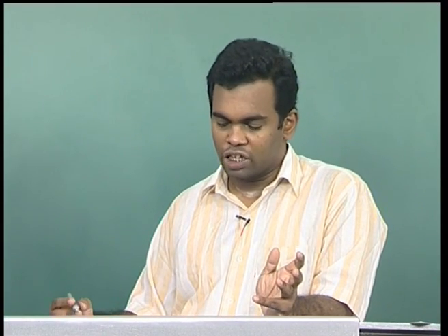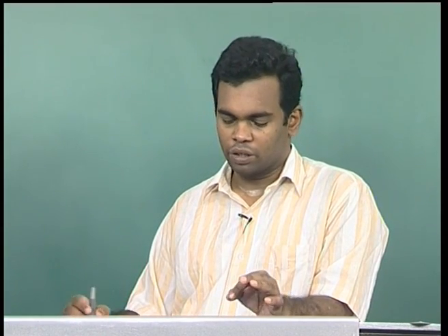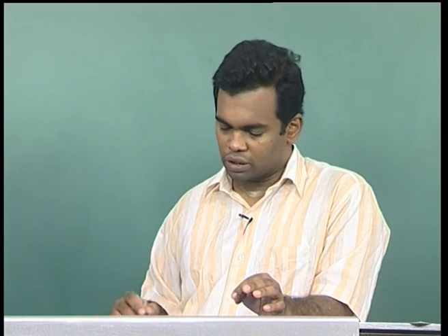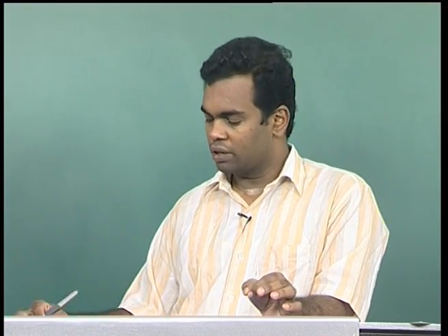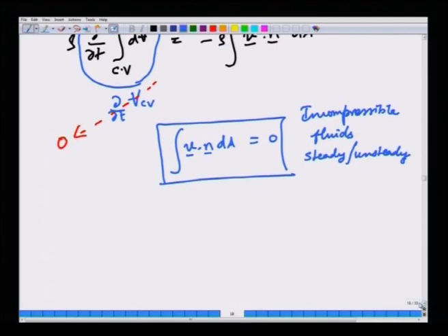Still, the quantities inside the CV could change with time, so the velocity can still change with time, okay, but that does not mean that this is valid only for steady cases. Even if you have unsteady cases, if the fluid is incompressible, then the integral of V dot n dA must be 0.